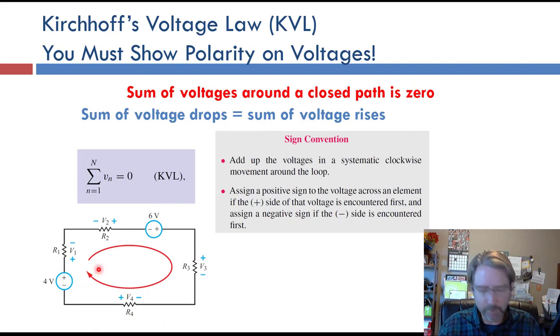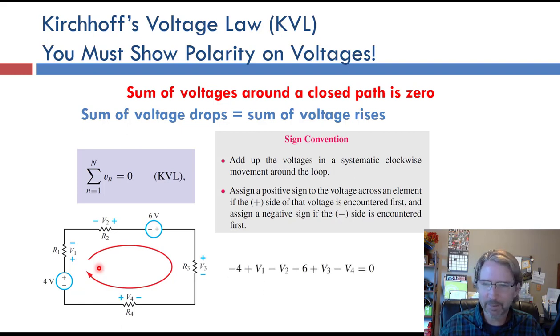So practice that, write them all down. You can pause the video. Did you get this answer? So here's minus 4 plus V1 minus V2 minus 6 plus V3 minus V4, and don't forget to write equals 0. That's Kirchhoff's voltage law.